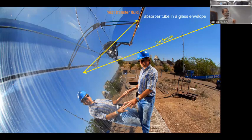And actually, the really good systems pull a vacuum between the absorber and the envelope. So you actually have very low pressures in that space. So you're also, again, trying to cut down on the convection from the outer surface of the absorber tube to the glass envelope surface. But on the inside of this, we have fluid flowing through that absorber tube. And so you've got heat transfer happening off of the inside surface of the tube into the fluid. And the idea is that we're going to heat that fluid up, and then you pass it through.